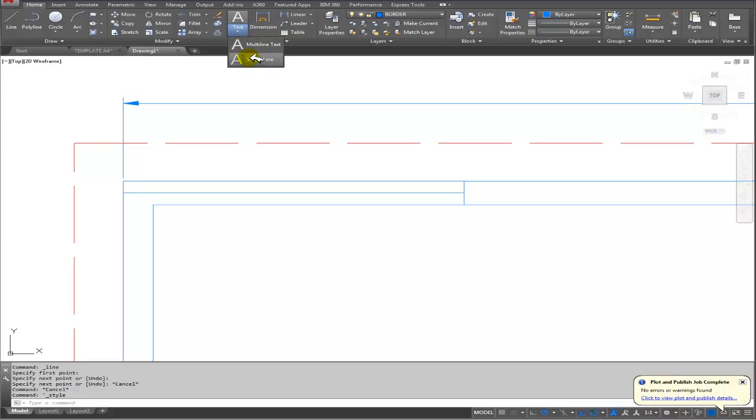So in this case, I'm going to use only the single text line. So I click single text line. And if you look at the current settings for the text, border is good. So that's the style we just used. Text height is 2.5. Maybe you could change that. Annotative, no. So the text is not going to be annotative. Justify is on the left. That's why I'm interested. Justification, I want this to be in the center.